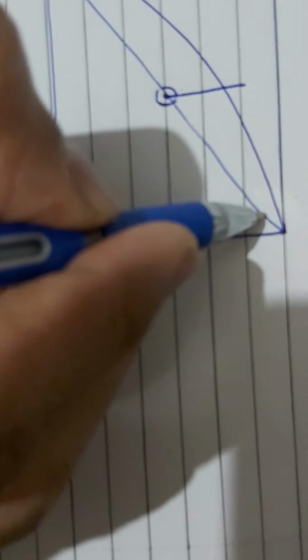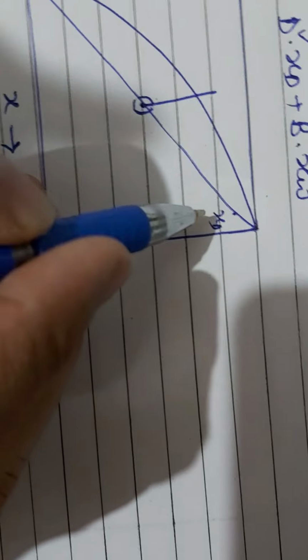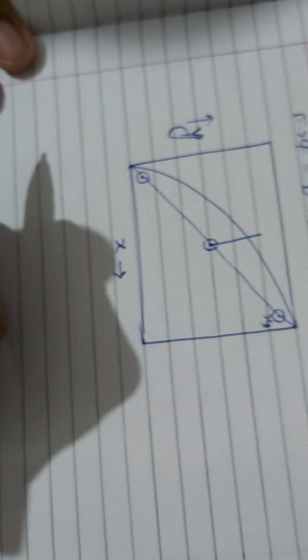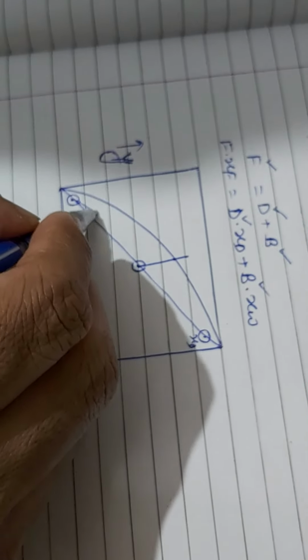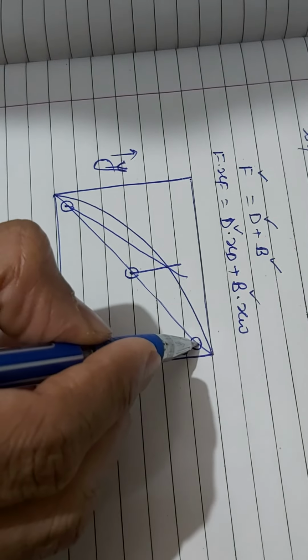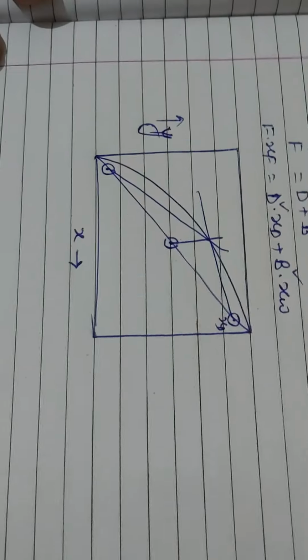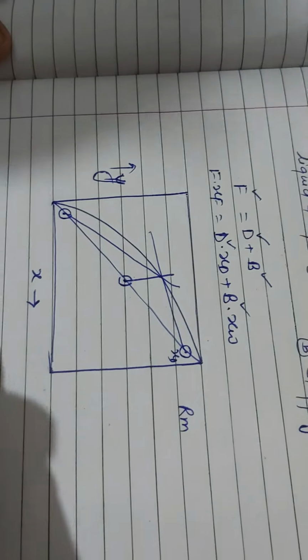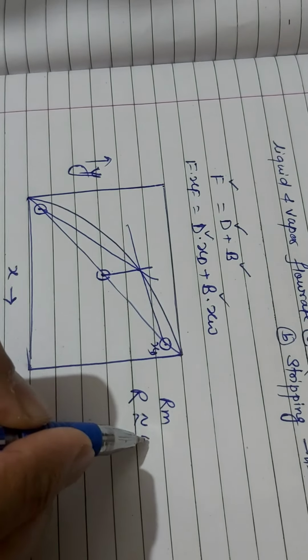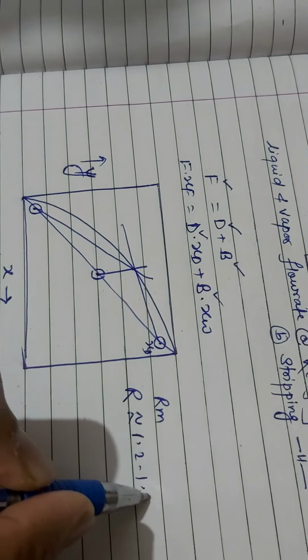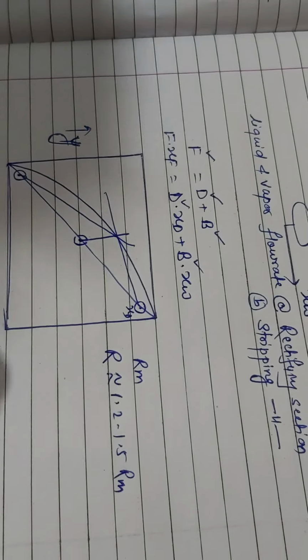Here you look at XD, distillate, and this is for the bottom. Wherever this meets the curve, you draw a line which gives the minimum reflux ratio, RM, and we are aware the actual reflux is normally 1.2 to 1.5 times the minimum reflux ratio.